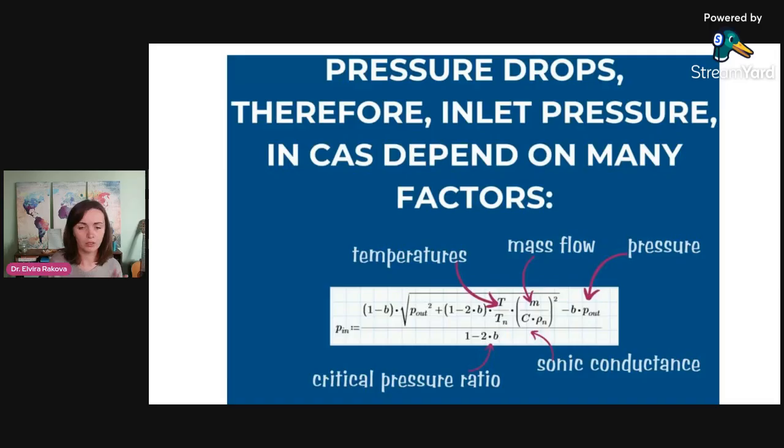So geometrically, what is happening there, or in this component, or in this pipe, where the geometrically this pressure ratio just achieves this critical sonic conductance in this point. And of course, for the piping, it's hard to optimize much the diameters or geometry. Usually this B is extremely important value for the suppliers of the valves. And now I'm already going into the lecture about this, but let me bring myself back.